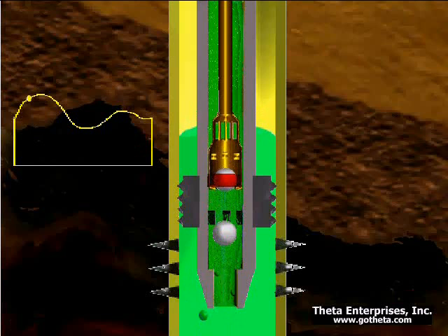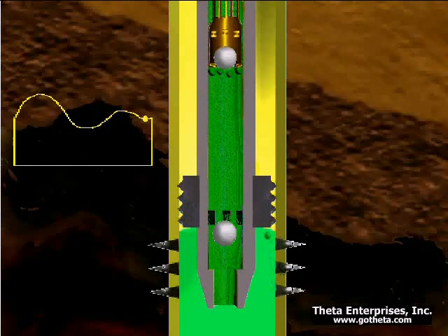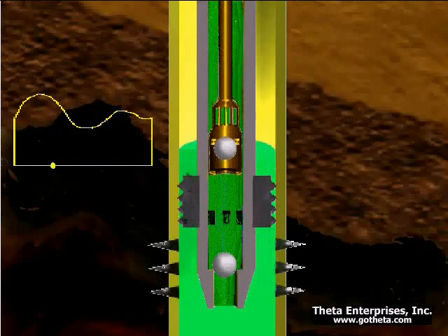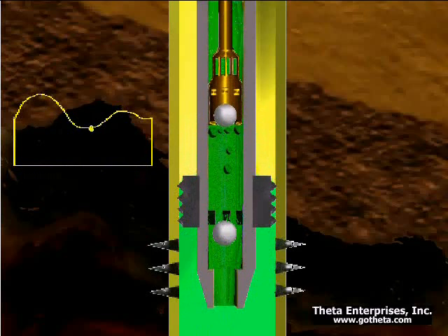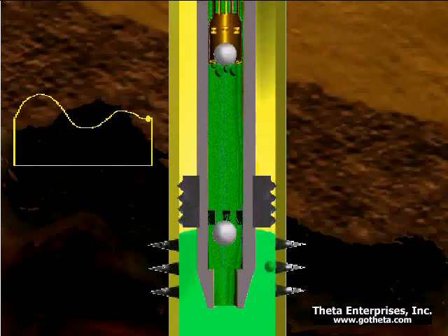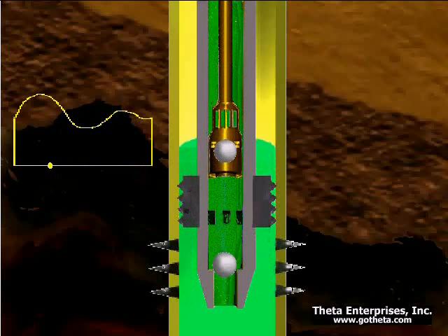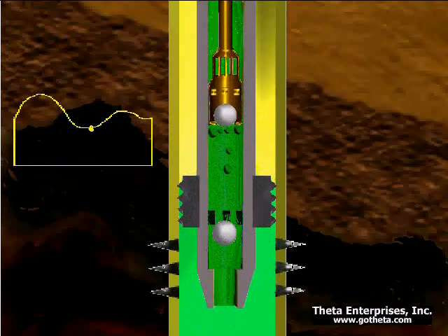Now we saw how the surface and downhole system works. But let me further explain this wave that I talked about with this animation. This is a group 2 well with high fluid inertia effects. And we use a red bar here to simulate the pressure wave that you put into the fluid when the plunger moves on the upstroke.